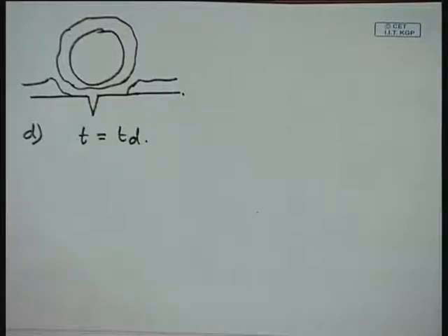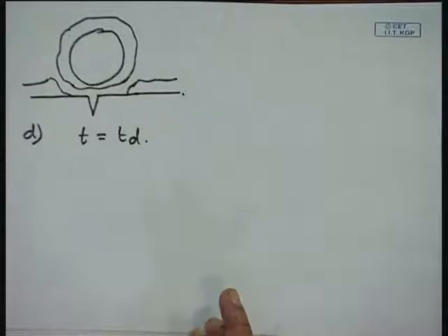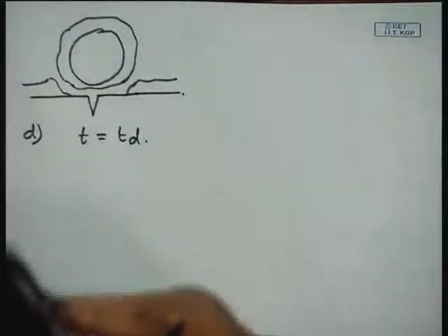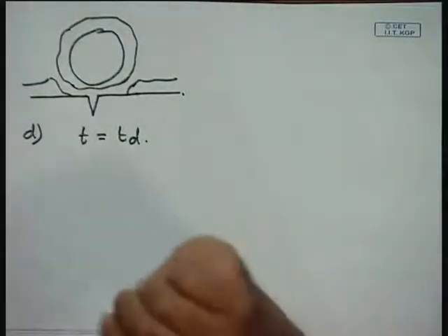Depending on the working condition, either it can be inertia controlled or it can be controlled by the heat transfer process, or in other words the inertia controlled process could be very small. Mainly the bubble growth is dependent on the heat transfer control process. Now, if we list down the parameters which are responsible for bubble growth and when we can have inertia controlled growth, these are like this.